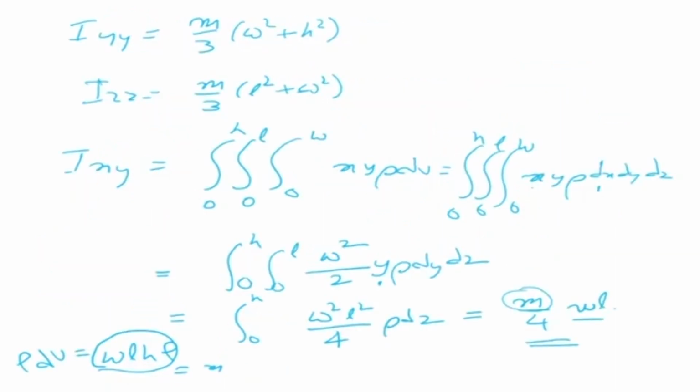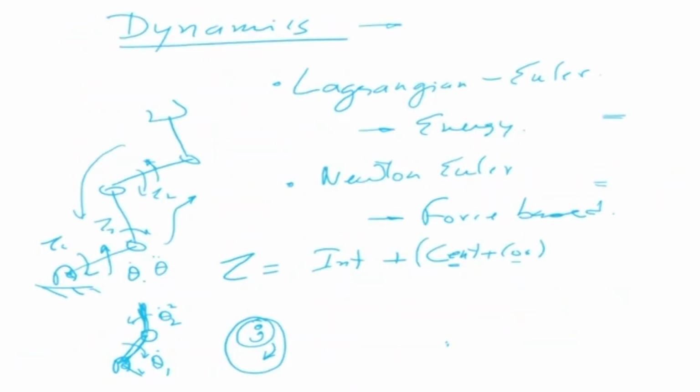Okay, so what we were looking at is the forces that the torque is made up of. What kind of forces? Inertia forces, because of acceleration, centripetal and Coriolis force, plus there is gravity which is acting. Gravity is always there, pulling the link down. So gravity is acting in that direction.